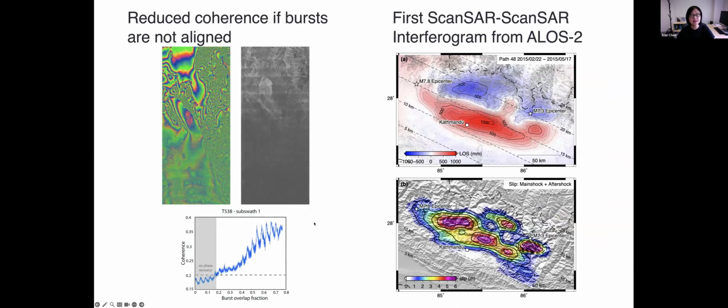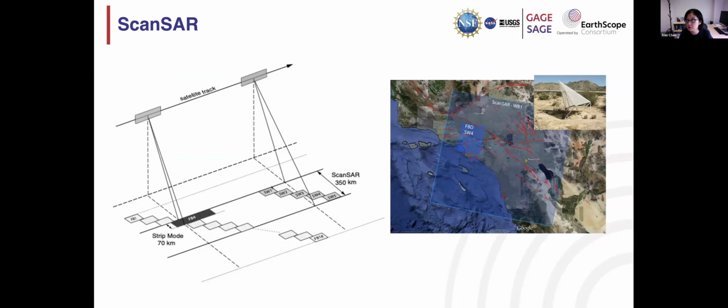And here are some additional limitations. Another foundational assumption that InSAR technology requires is this: when you have multiple SAR images, what InSAR really computes is the phase difference between the two SAR acquisitions. So there is a requirement that the radar satellite be in a frozen imaging orbit.